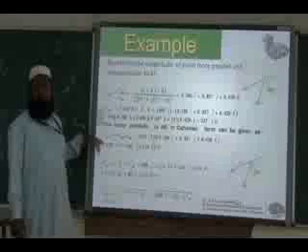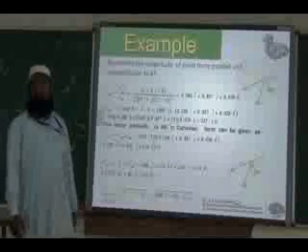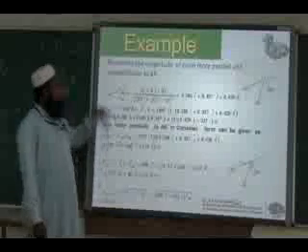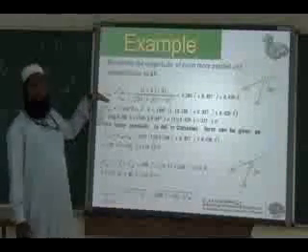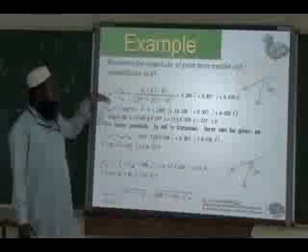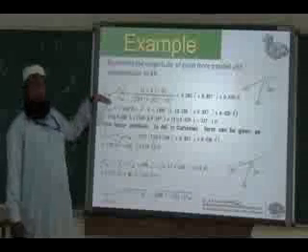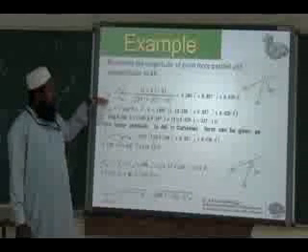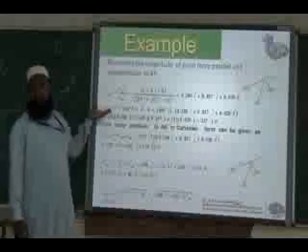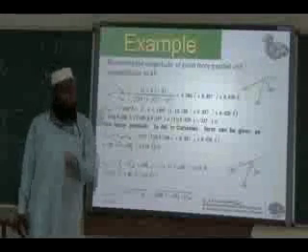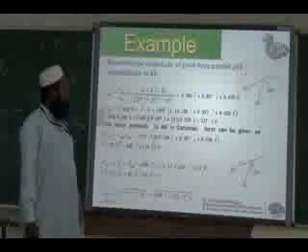Vector AB is parallel component, then perpendicular component. So in 4 steps: first position vector, 0th step, then unit vector along AB. In order to represent FAB in Cartesian form, first we will find the unit vector. Then using your dot product concept, we find the scalar for AB, the scalar along force line AB.